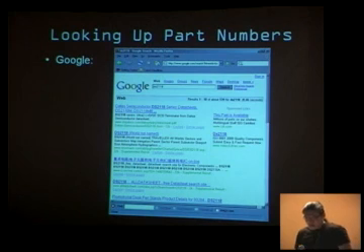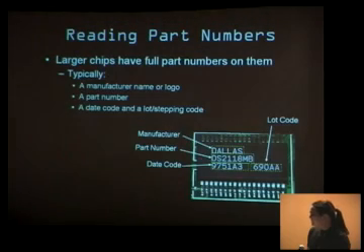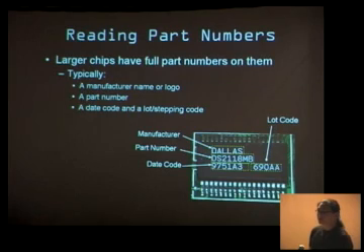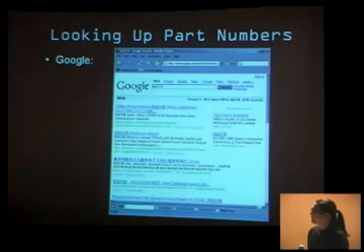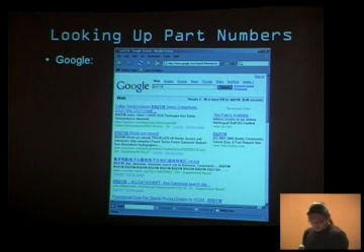If you want to look up a part number, I know there's a talk really about cuckoo on Google, but I'm an old-fashioned guy and I use Google. Did Google just come out? Anyways, if you just plug in the part number, like you saw here, DS2118, I took off the suffix MB. You put it in and you see right away: this is a Dallas Semiconductor Ultra 2 LVD SCSI terminator, right? So you know exactly what that chip is. Great. Google works great for that.